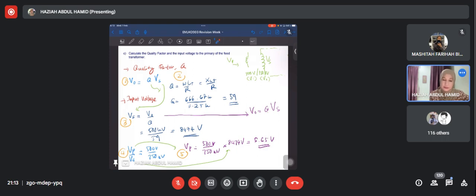volt. If you remember, I said the other day that even though we have a transformer feeding our resonance circuit, or testing transformer, we still have means to control the input voltage by using a voltage regulator. So we raise the voltage gradually. We don't just directly take 100% of the primary or transformer rating.